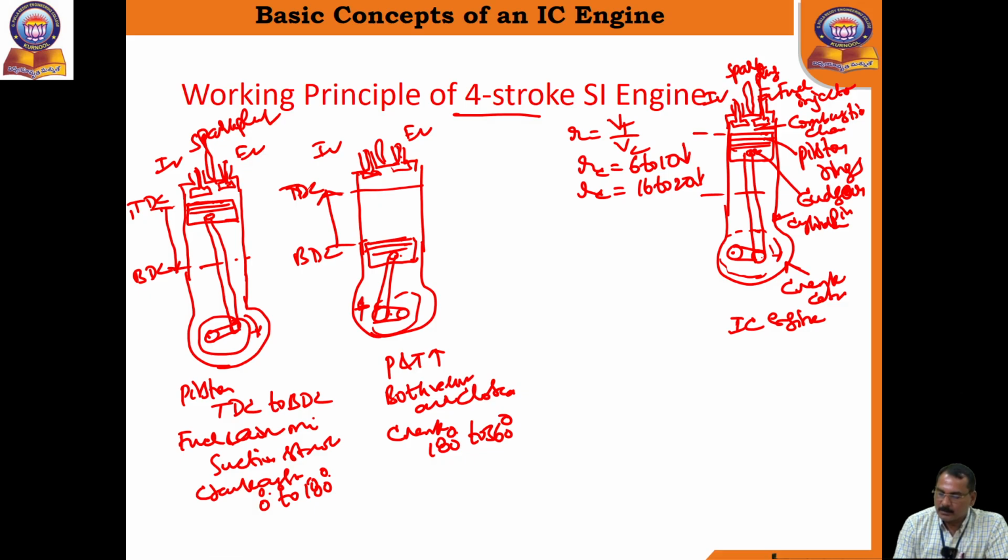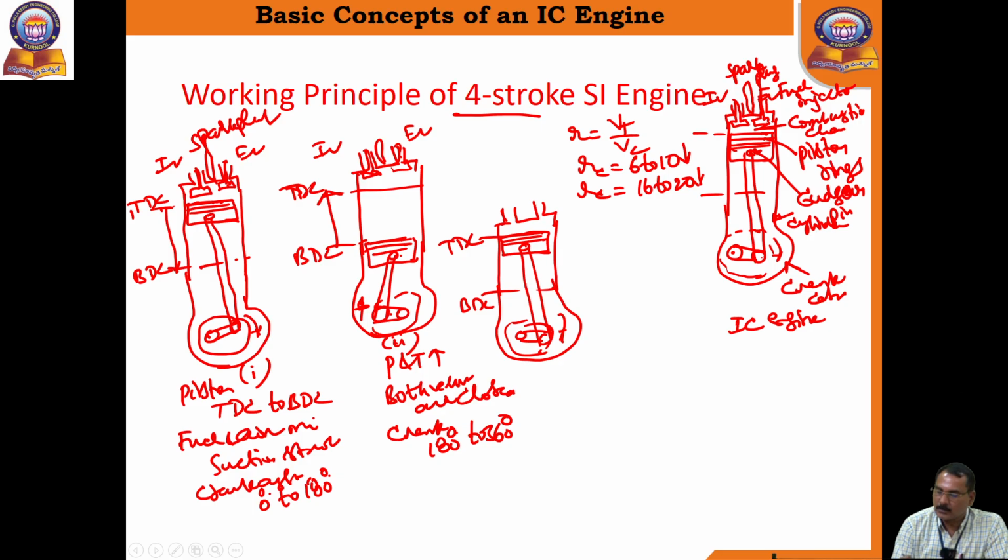This is second stroke, that is nothing but compression. The first one is suction stroke. Then coming to expansion power stroke first. So when the piston is at top dead center, so here what happens, so spark plug, both valves are closed. This is third one, that is nothing but power stroke.